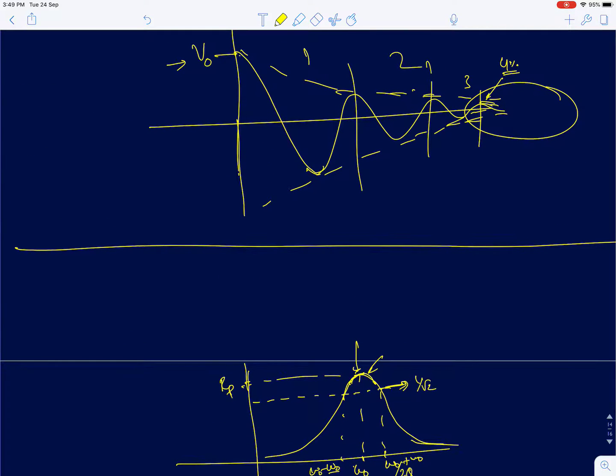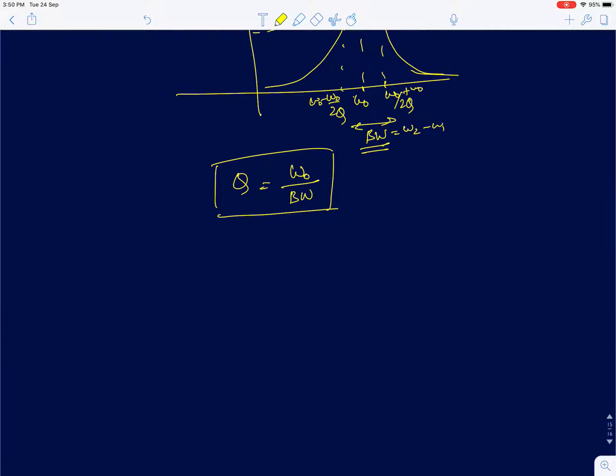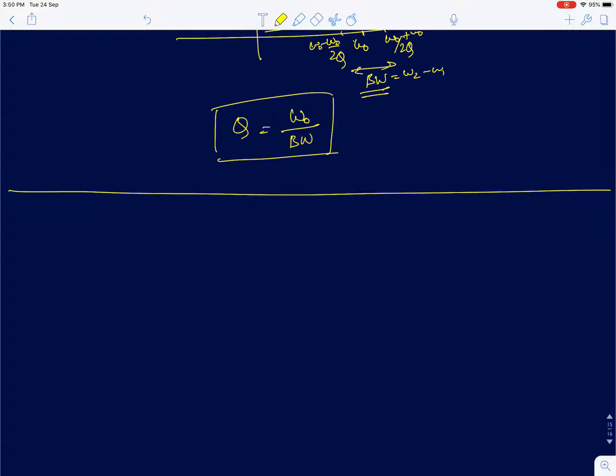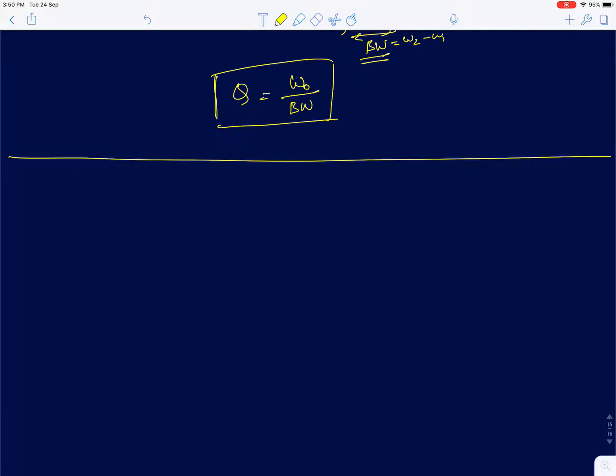At the same time, if you are given the time domain response, you can also find the value of Q from that time domain response. Okay, from the time domain response you can also compute the resonant frequency and all that. But Q is one important thing. Visually it's very useful for circuit designers. By just looking at the waveform, to a first cut, you can very easily predict the value of Q from the time domain response. Okay, so that's it about Q and impulse response of parallel RLC circuits. So now I'll try to give a small intuitive explanation